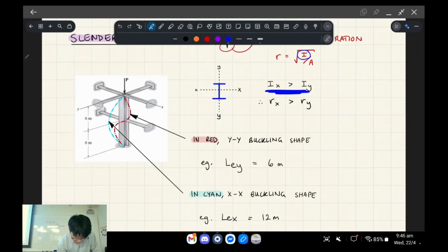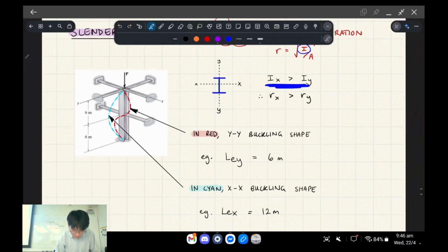Restraining it halves the buckling length, and therefore it has to buckle like an S shape instead. A lot of the time in buckling design, you're comparing the moment of inertia or your radius of gyration by how long its unrestrained length is. That's the idea.